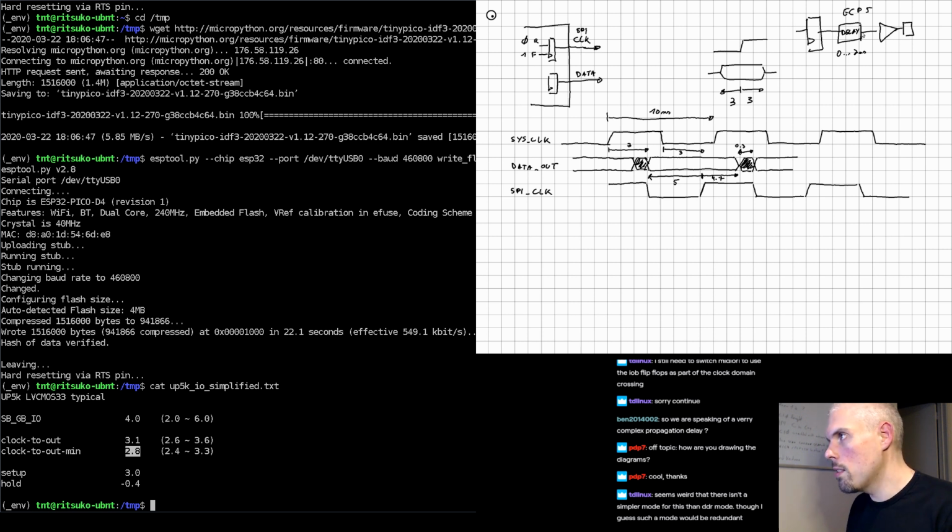If you want an example of using the O delay, you can look at the RGMII PHY in LiteX. The LiteEth PHY uses the output delay block for the transmit side timing. If you want an example of the 90-degree phase clock, you can look at my iCE40 playground repository.